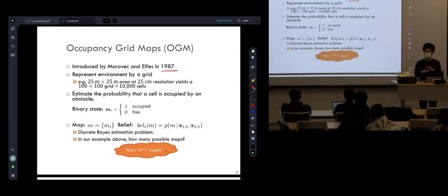It captures the correlation that you have between different points in the environment. If this is a table and there is a point here that you observe and it's occupied, there's a really good chance the nearby points are also occupied. So that structural correlation can help you to have better, more accurate inference, even though the point cloud observations from the sensor are still sparse and noisy. So a better model can give you better results.